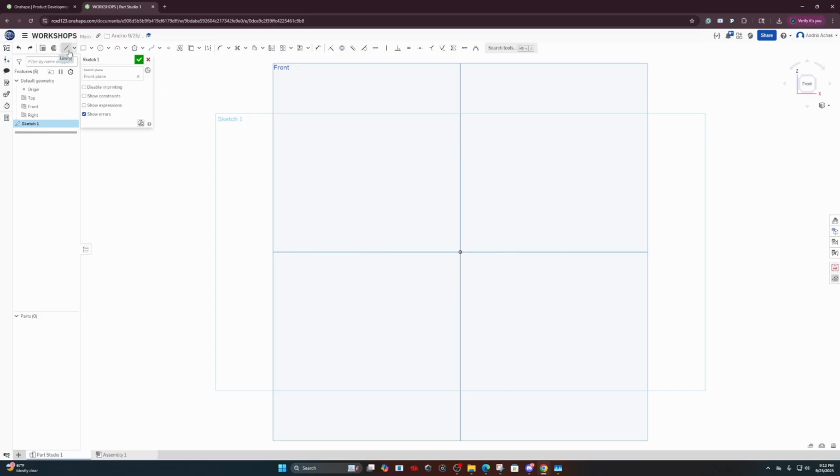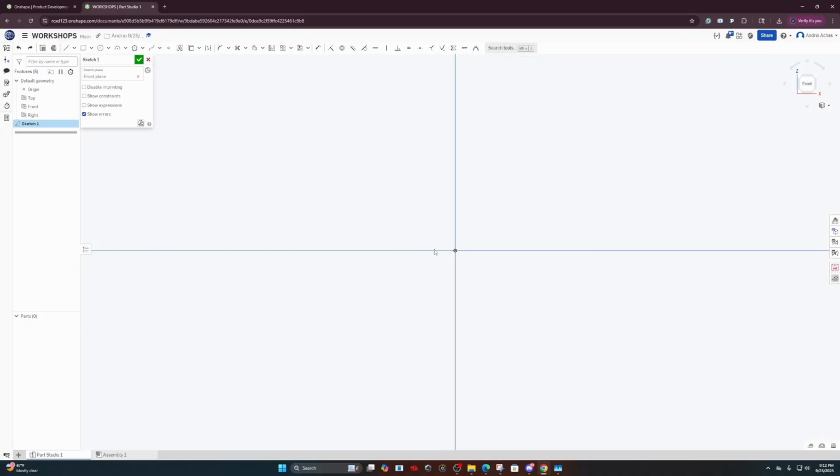And as you can see, let's try making a square. The way you want to start by making any sketch is making it based off the origin, which is right here. So let's start from the origin. And you know you start from the origin when it's highlighted yellow like this. And let's just say you press here, you messed up, you don't have to click again and delete it, you can just press escape and it just ends that tool. And another way you know you selected a tool is when it's highlighted this gray color. And that's how you know you've selected it. And if you want to deselect it, just press escape.